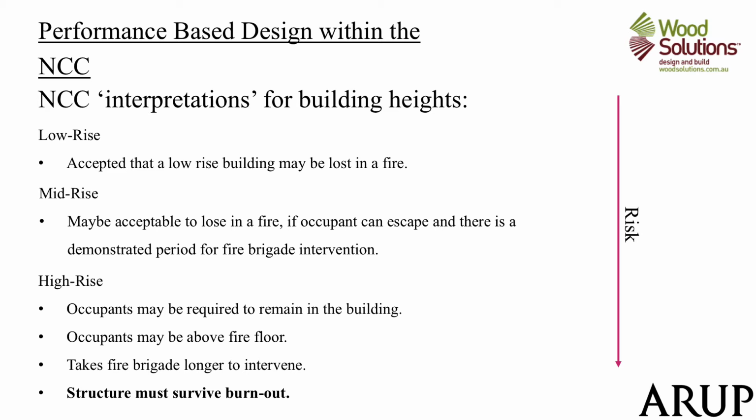Now when we move into mid-rise construction, as Paul touched on, we've got more occupants in the building, and we need to have consideration that there's been enough time for all occupants to escape. There's been a demonstrated period for fire brigade intervention, and typically that's got a large factor of safety on as well. So that's either from a prescriptive viewpoint or from a performance aspect. That's meeting the deemed to satisfy FRLs, or if we're looking at a performance-based assessment, we're demonstrating how that's achieved.